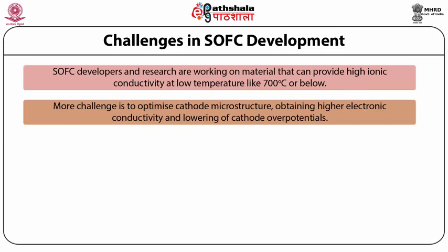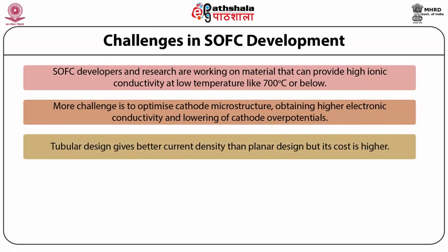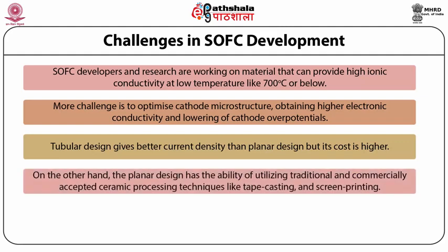Both tubular and planar designs have their advantages and disadvantages. Tubular design gives better current density than planar design, but its cost is higher. On the other hand, the planar design has the advantage of utilizing traditional and commercially accepted ceramic processing techniques like tape casting and screen printing.